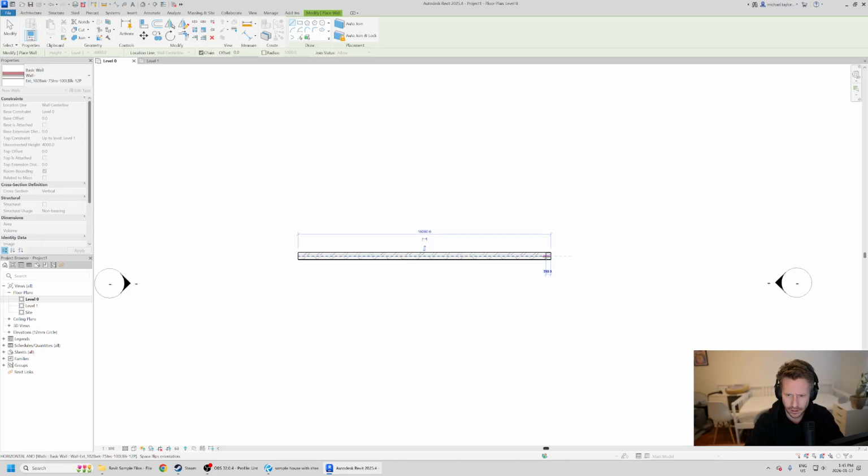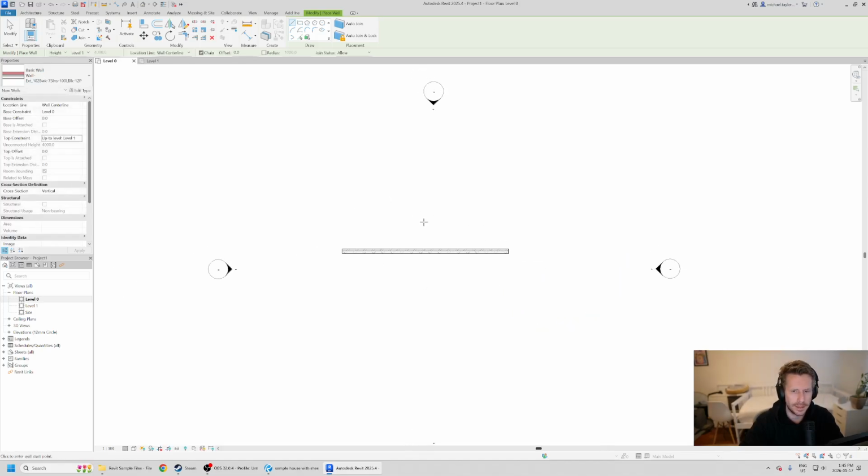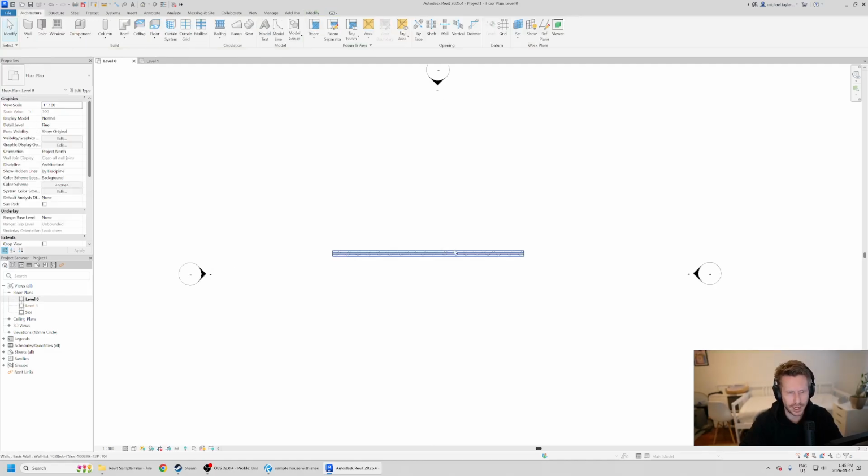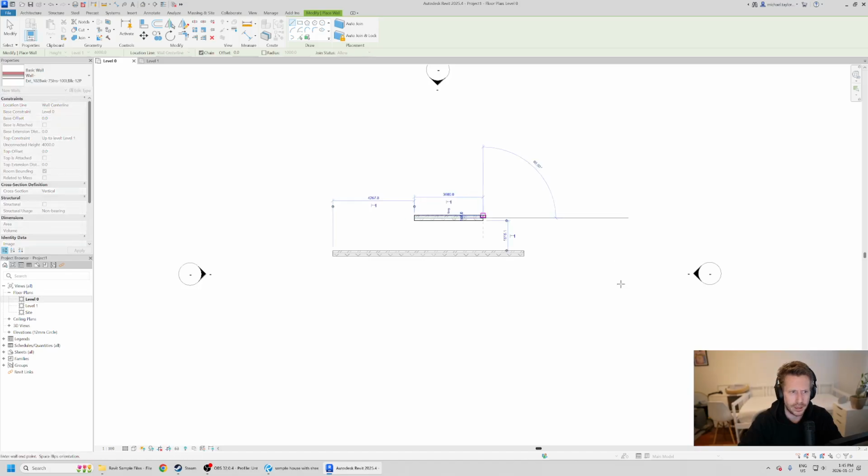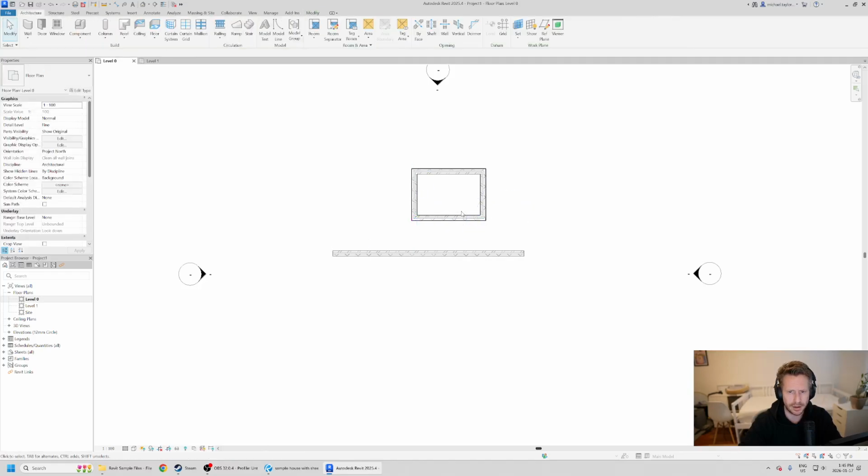If I hit enter, I should see that wall become modeled, right? So one wall, that's it. To get out of the command, you're going to tap escape. To get all the way out, we're going to double tap escape, and you'll see our properties palette has come back to our view. That double tapping of the escape key will always get us out of the command, with a couple exceptions. But I'm going to come back into my wall command here, and normally I can chain my walls together, and I'm going to double tap escape here.